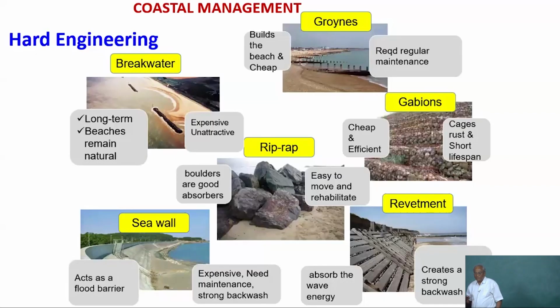So what is hard engineering? You have breakwaters, where you can have the offshore detached breakwater. When you have a structure like this, it will undergo the phenomenon of diffraction at the tip of the breakwater on either end.